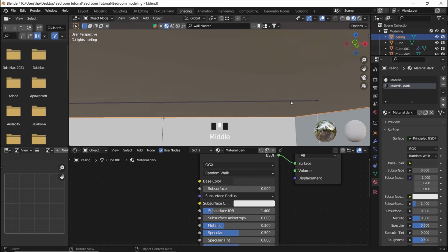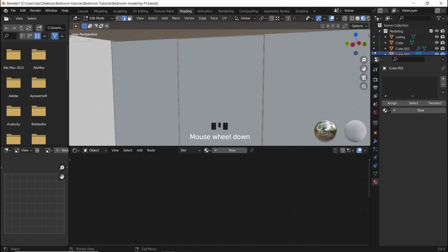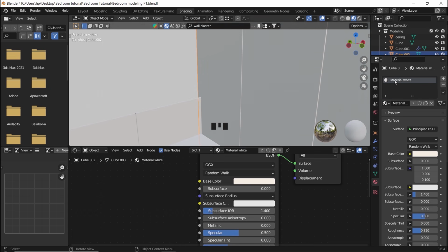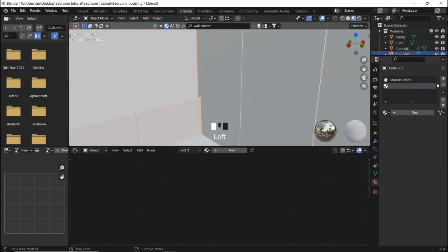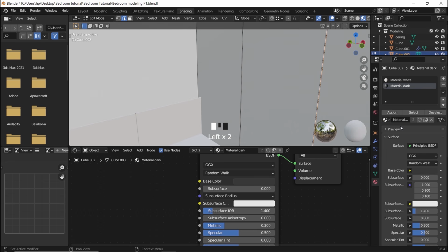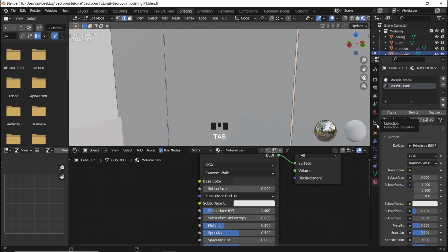We can now add those two materials to any model we have or made by assigning it to the model or using Ctrl L to link copy materials data around the scene. To finish the scene, we need to bring the remaining models we will use for this shot, and that will be the curtain, the window, the carpet under the bed, with some books and a handle model for the cabinet wall. So play some cat music and have fun arranging those around the room.